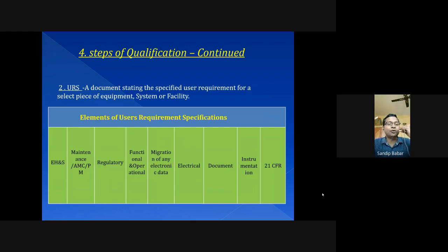It should have a safety valve on the fermenter lid also. Then for temperature safety, it should have insulation of the pure steam inlet and chilled water inlet. These are the safety features. Then you have to ask the vendor what type of insulation you require. The insulation should absorb the temperature of the inside line, and it should not give a temperature above 40 or 45, which is harmful to the user. These are the safety features.